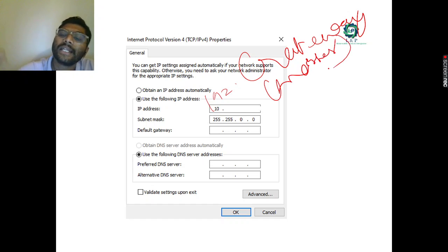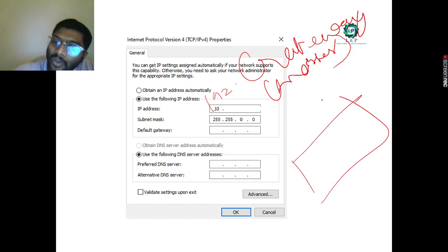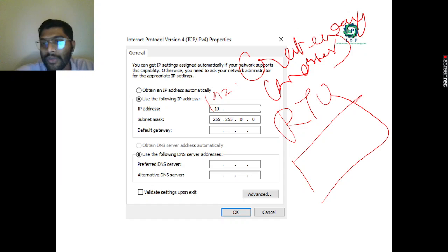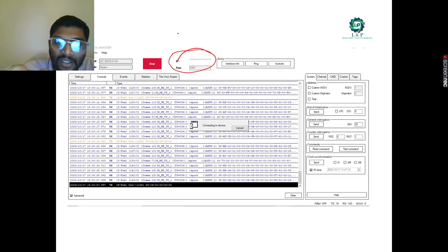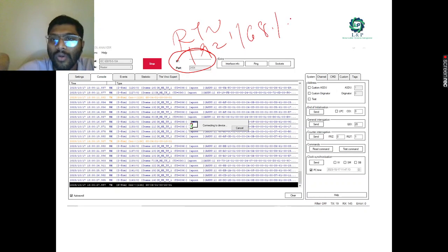And on the other end, if you're going to access any sort of RTUs or gateways, that address you need to provide here. Here you had already assigned it. The RTU that you're going to assign, you need to use 192.168.1.1 or .2, like that. So many things will be there based on the concerned setup. You need to connect it here.